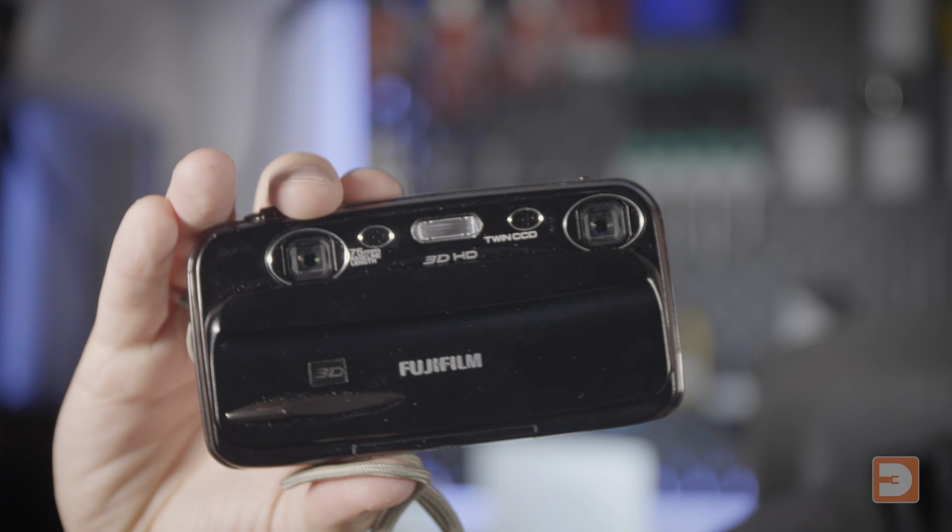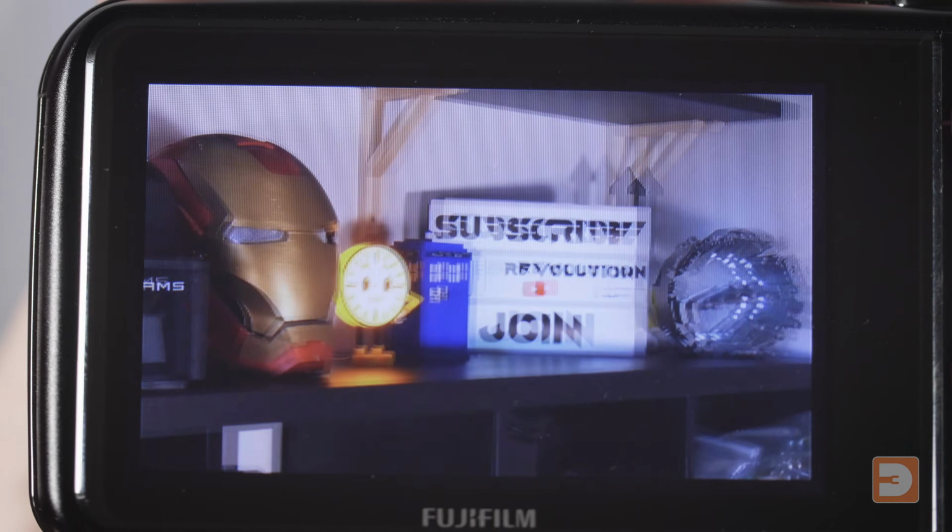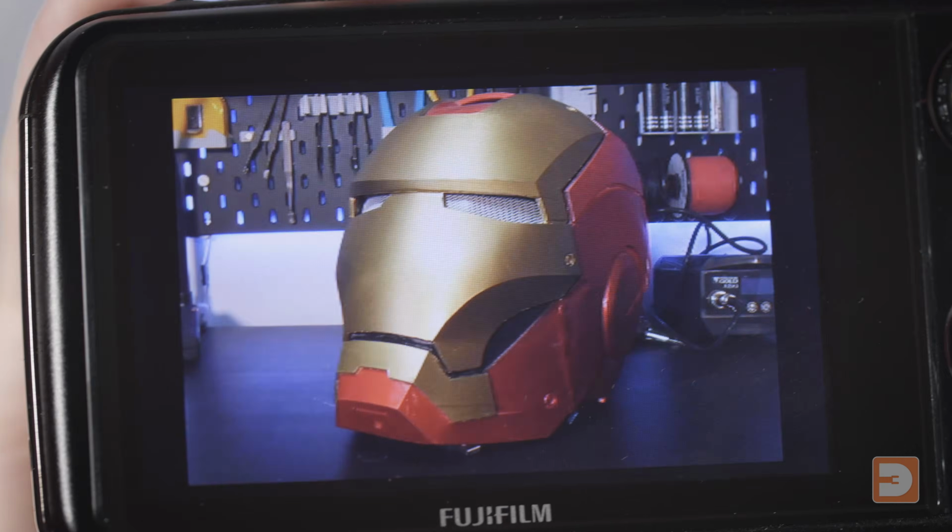Then you apply a thin lenticular lens on top, which refracts the light in a certain way, which only shows you one of the images located beneath it depending on which angle you're looking at it. As a result, this can work with any 2D image providing that the lens is lined up correctly. So this camera with two lenses on the front takes two different images from slightly different perspectives and can then show a 3D effect image on the back using its lenticular display.